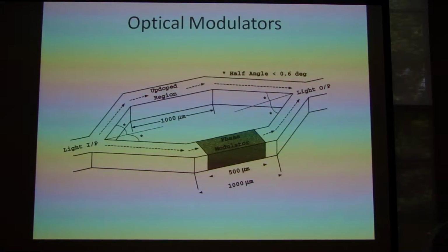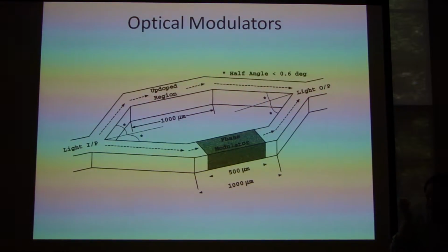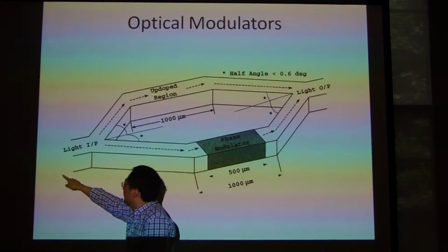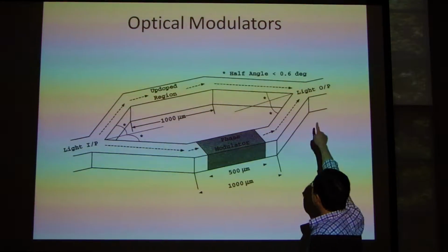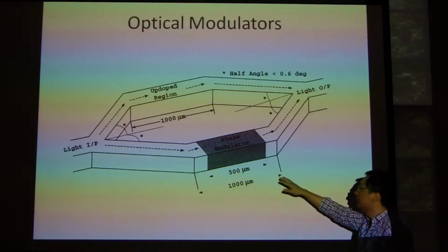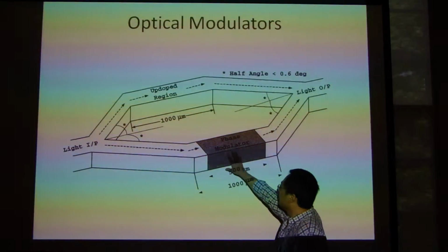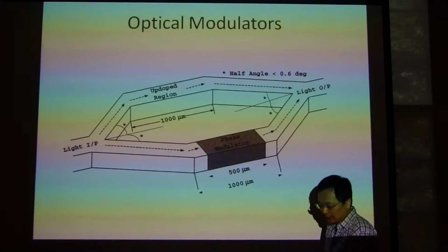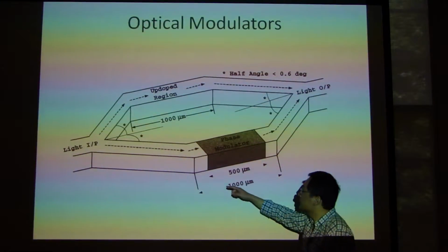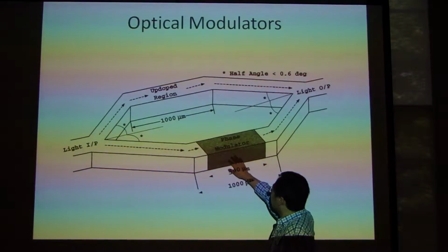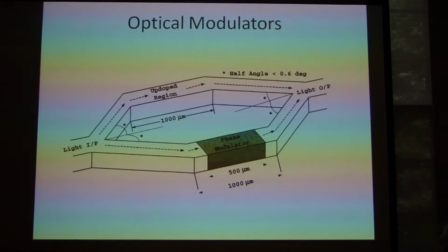And you also have modulators. A modulator is something you use to turn a light signal on and off externally. Say light is coming in here, and that's constantly on. But you control one arm, and at the other end it's on and off. Say you have 1010 here, you also get 1010 at the other end. Usually people use the so-called Mach-Zehnder structure. They change the refractive index, right? When you change the refractive index, then the phase accumulates in this path, and the other path is different. Then you use interference, and you can create this 1010 idea.